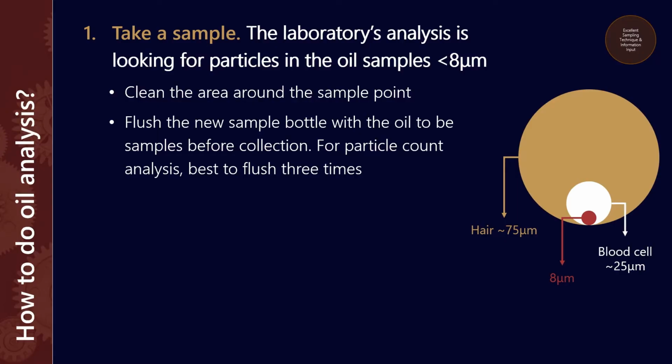Right, so even though a sample bottle might look clean, it's really important to flush new oil bottles because it is entirely possible that they have been contaminated. If you're doing particle analysis of a very crucial bit of equipment, let's say it's a hydraulic pack with very tight tolerance servo valves, then in that instance, you would probably want to flush the bottle a couple of times to ensure that it has not been contaminated. We also want to clear around the actual sampling point as well, because we don't want that to contaminate the sample.